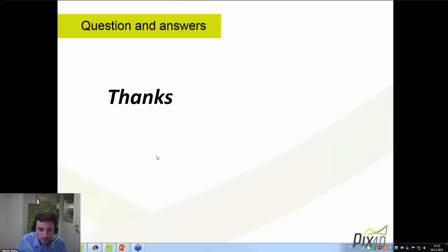If I was to import the raw images into Photoshop before importing into Pix4D and adjust the lighting, would that help with matches? For some projects, it definitely would, but you have to be careful when you are changing the raw images in Photoshop not to do anything which is harmful to the geometry of the images. And by that I mean you should not try to correct for the fisheye effect or for the perspective effect in Photoshop. You should just limit yourself to doing the lighting.